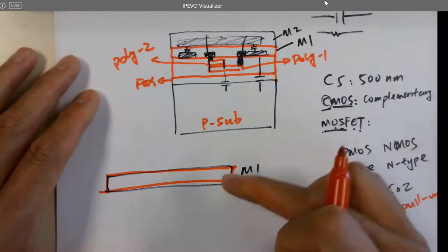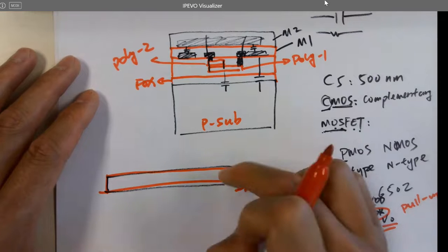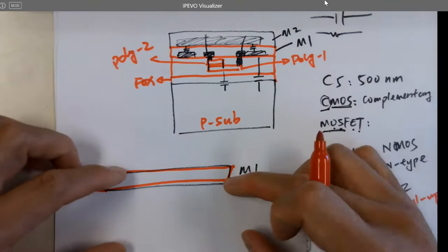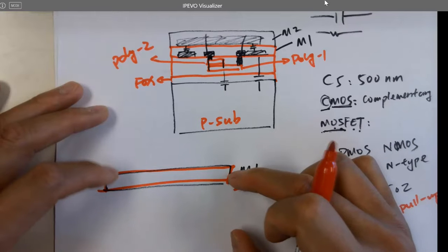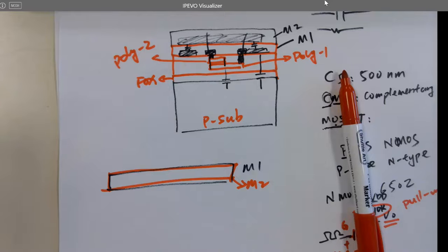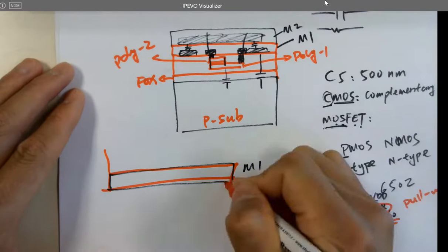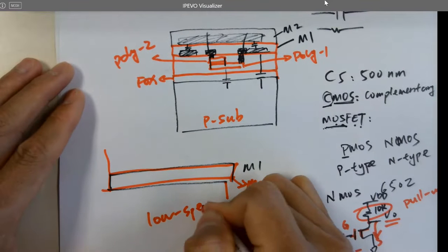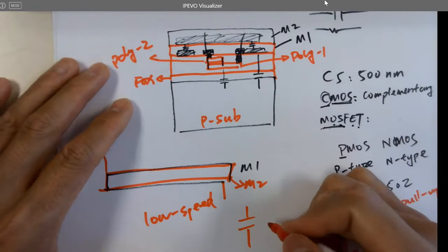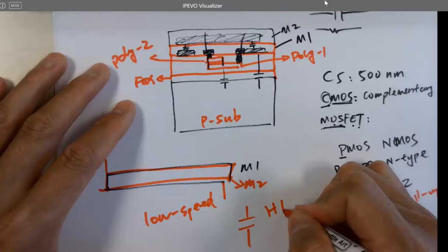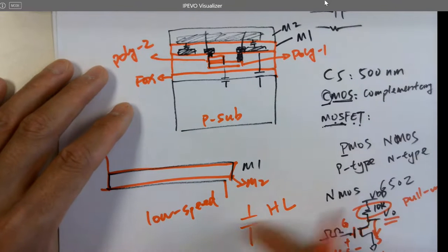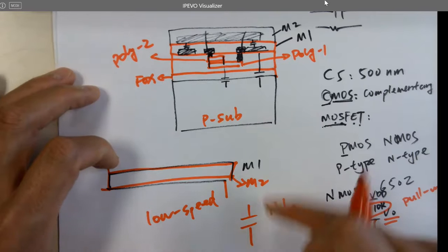No, there are different layers. It's not doing anything. So is this recommended? No, why? It forms a huge what? Parasitic capacitor. You got a metal 2, metal 1, right? It's a cap. So if you are using a very low speed circuit, it probably doesn't matter, because the caps pass what? High or low frequency? High. Okay, if you have a high frequency, high speed circuit, this matters.